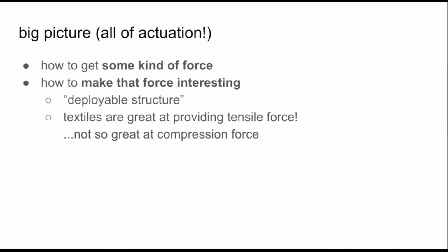Okay, deployable structures. How does that relate to fabric? The umbrella one, I think, was actually a great example. That's fabric. And it shows something that comes up again and again when you're working with fabric, which is that textiles are great at providing tensile force, terrible at compression. So a lot of times when people think of fabric, they think of fabric as weak because they think I can just push fabric and it'll just buckle. And okay, that's true. You can just push fabric and it'll buckle.